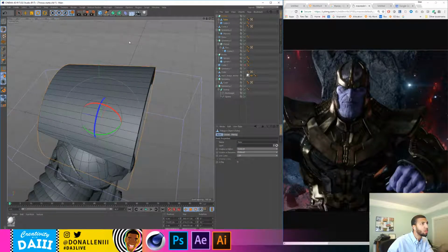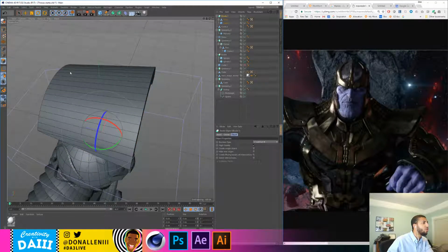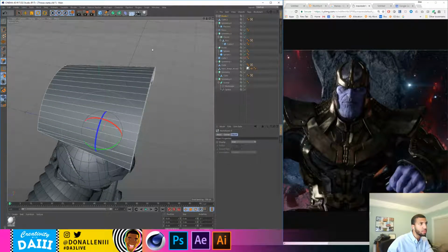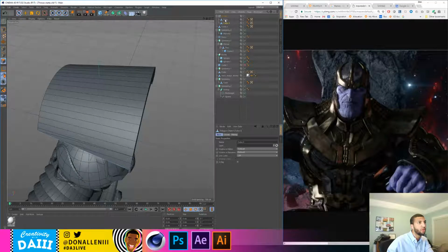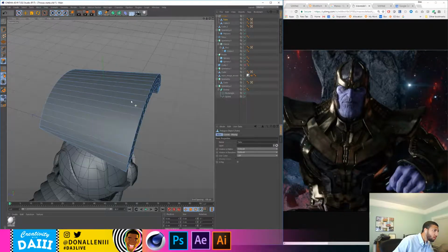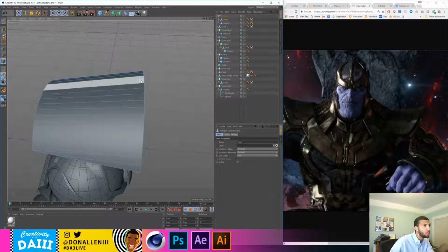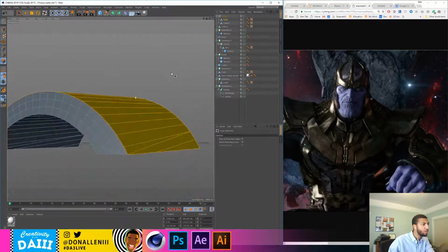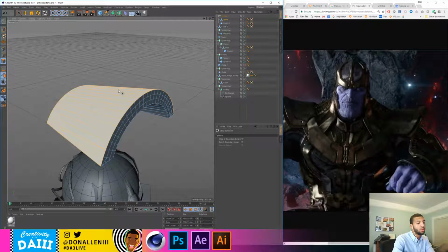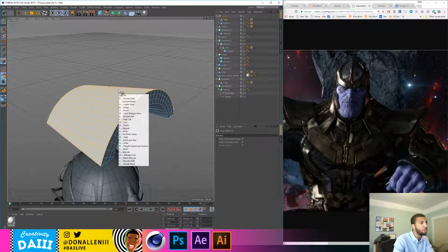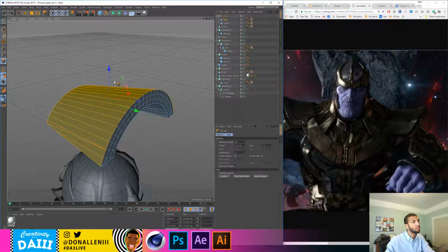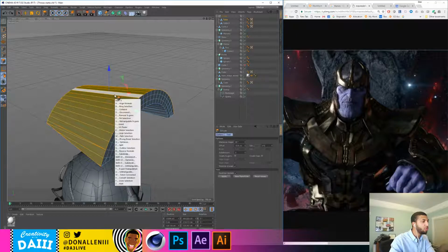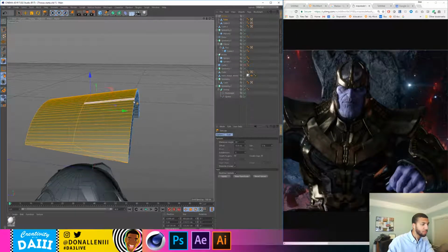So we're going to turn this into a solid object, and we can go to our face selection. With our face selection turned on, if we go to this shape now, we can grab individual polygons, and I want to do a cut. So we're going to do UL to loop select everything. That's going to grab everything in the loop here, which is great. Now we do subdivision, which is MT. Actually, that's the wrong one. US is subdivide. Let's do that again.